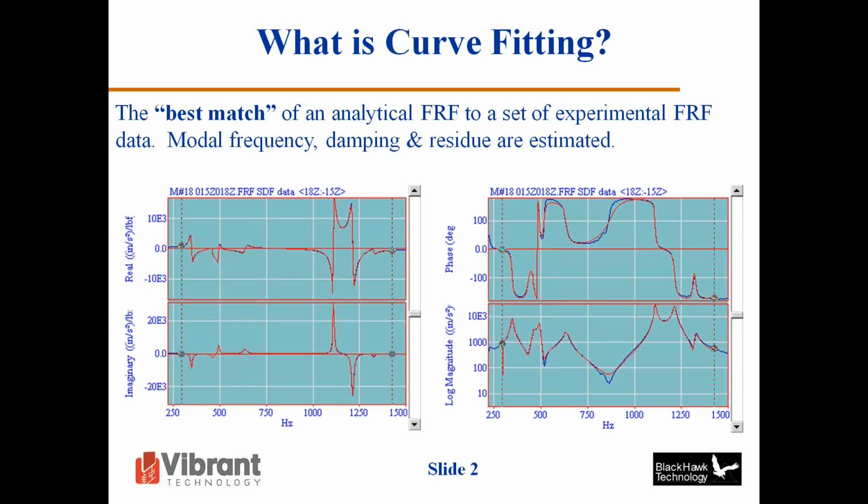Bode was a guy who first started drawing these plots by hand, and typically it would be a log magnitude, log frequency plot. Here we have log magnitude, linear frequency, which we normally use in modal analysis during curve fitting.